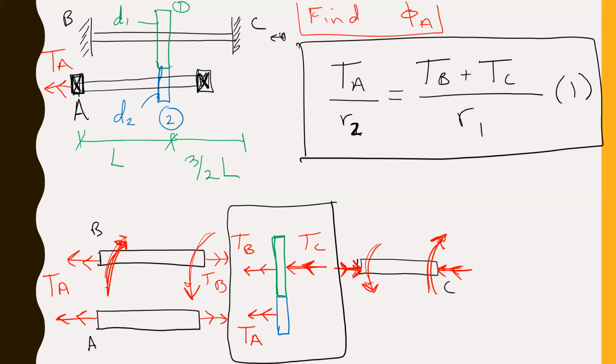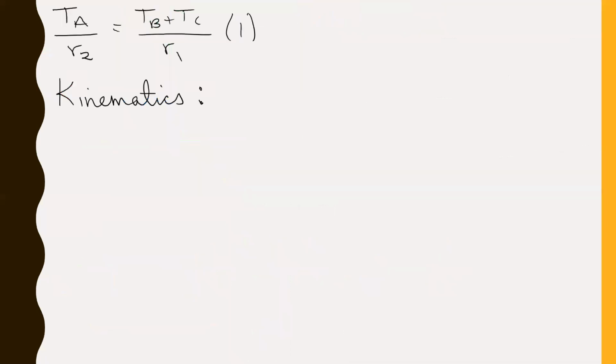So when you twist it at the gear, you're twisting one direction and then twisting back the other so that it has a net twist of 0. Good. So that's our kinematics observation. So what that says is that the twist of C relative to B is the twist of gear 1 relative to B plus the twist of C relative to gear 1, and that equals 0.